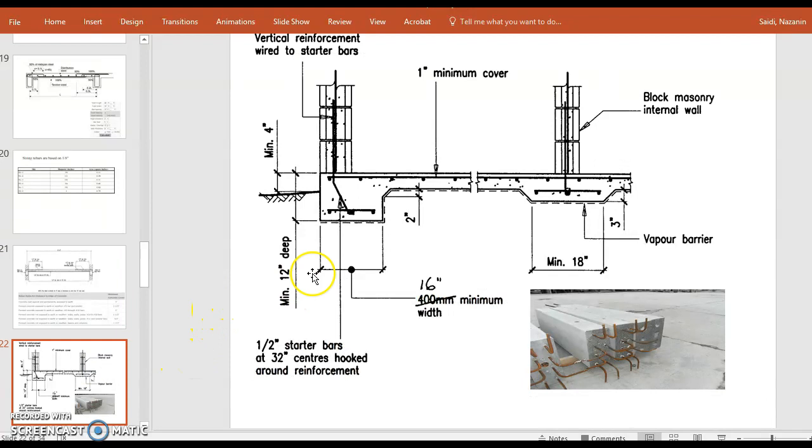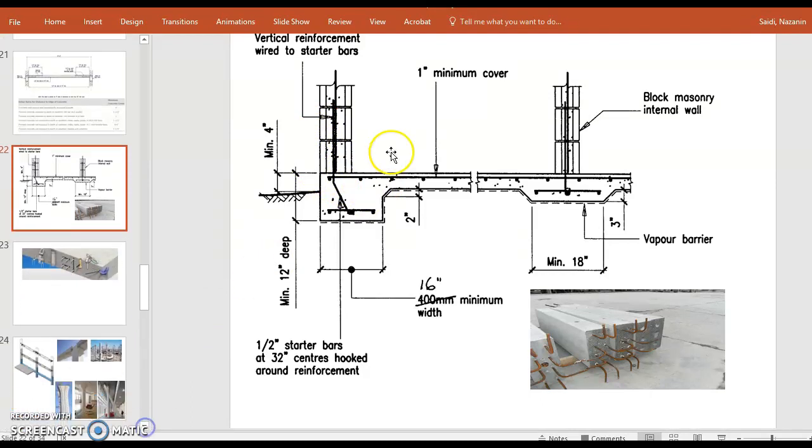Connection of the slabs plays a major role, whether you're connecting the slab vertically to a structural column or wall. This is a diagram which is somewhat outdated, suggesting a CMU wall connected to the slab. Very similar to our school, but this system is outdated. But I just wanted to show you, so when you see these reinforcements sitting on the ground, they get connected as such.